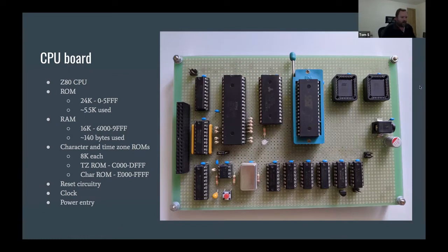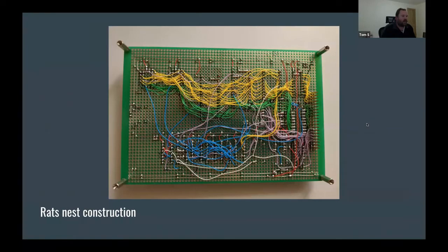So that's the front side of the board, and then the back side of the board, if we'll proceed. I've chosen to go with rat's nest construction, and this is my preferred prototyping method these days. I've also tried using VeriWire. If anybody else has tried that, you lay down these little comb structures between all of your chips, and provide ways to route all of the wires around your board. But trying to troubleshoot something like that afterwards is very difficult.